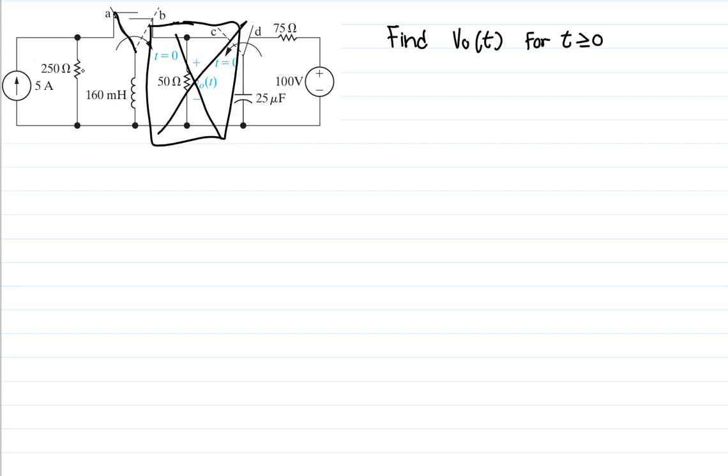and that circuit. So to find the initial inductor current, we're going to focus on this part of the circuit since the inductor is on this part of the circuit. So remember, the inductor, when a circuit has been closed for a long time, the inductor turns into a short circuit. So which means that here we have a short circuit before t is equal to 0. We only have just the wire over there.